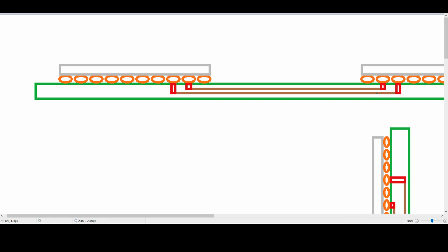You might have seen this with a lot of recent motherboards, that they put a ground layer essentially above and below the memory traces, so that there's less interference between different conductors, and that ground layer essentially shields it from other conductors that are moving through that area of the board.